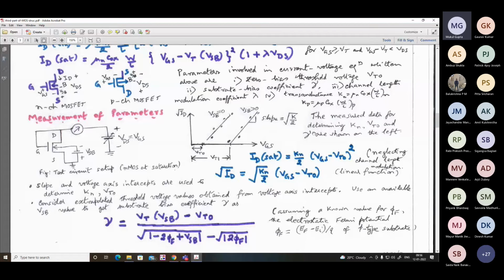power 20, whereas if you look at the acceptor concentration, that was 10 to the power 16. Also, if you consider the intrinsic silicon concentration, that is even lower, 1.45 into 10 to the power 10. So if you compare these values, 10 to the power 20 is orders of magnitude higher than the lightly doped p-type substrate.